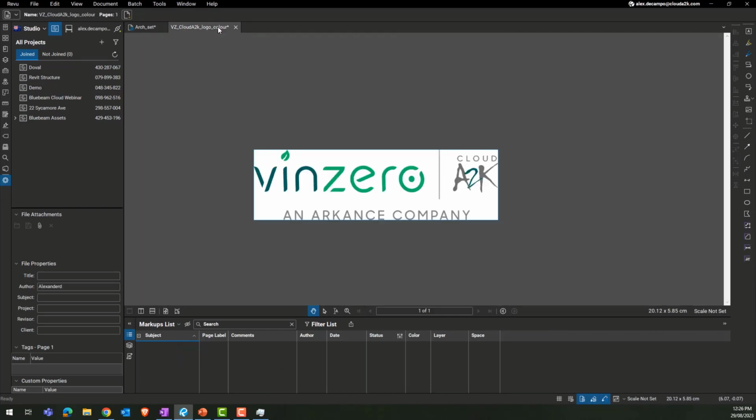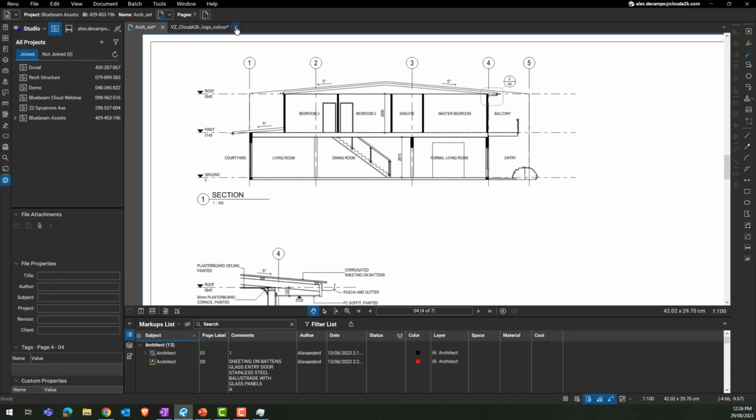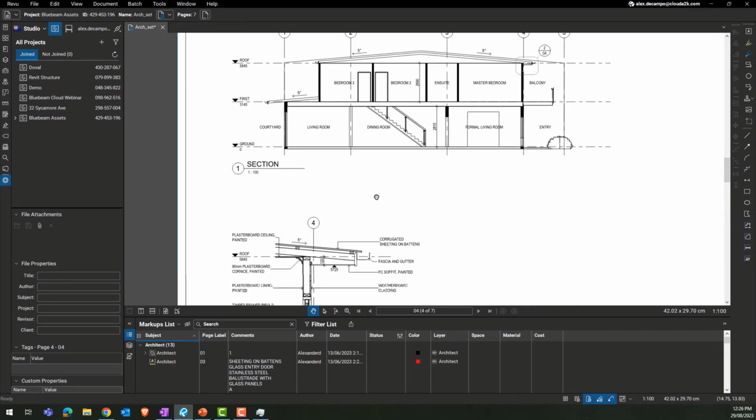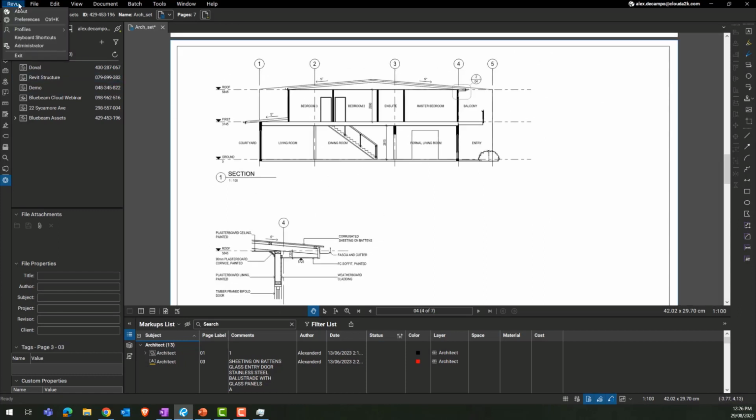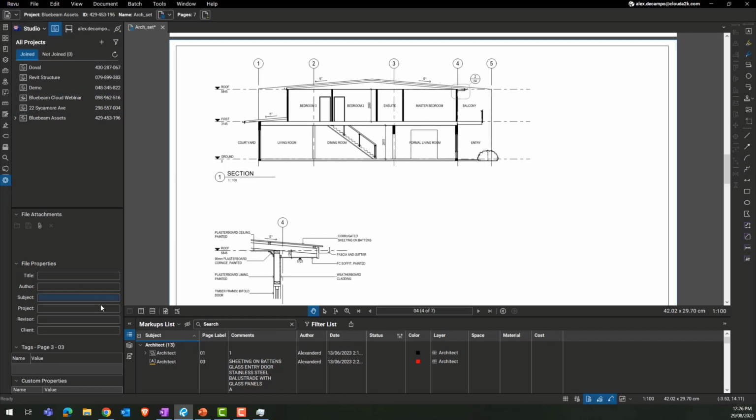Anyway, carrying on a little bit, so that's the customization side of it. The next bit is the cool tips and tricks in your profiles and in your preferences. The first thing is profiles. Once you have a layout like this that you are happy with, you can go into review profiles and save that profile somewhere. I can save that to my desktop, or anywhere I want, so I'll remember it.